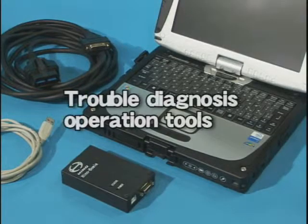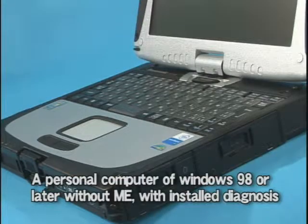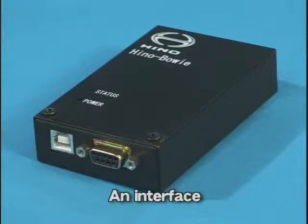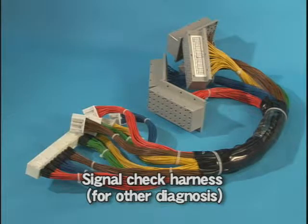The tools used for actual trouble diagnosis operation are three items: a personal computer with Windows 98 or a later version, on which the diagnosis software is installed, an interface, and a connecting cable. The signal check harness is a tool that you can use to check each component failure or harness disconnection.